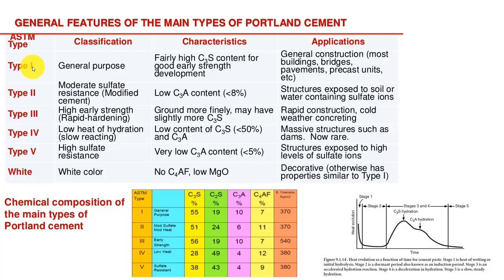On the other hand, if you have a moderate sulfate resistant cement, it would have a tricalcium aluminate content lesser than 8%, so that the surplus tricalcium aluminate would not be there in the cement matrix to induce delayed ettringite formation or some other durability problems. Thirdly, you have a high strength cement which has a high amount of tricalcium silicate, which increases the early strength gain.